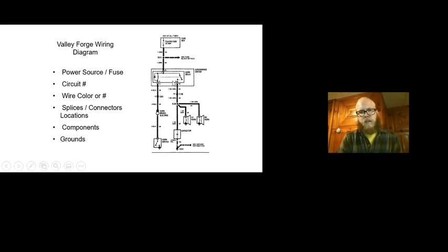On this, you see how the fuse panel is all dashed. That means we're only seeing one piece of this fuse box. There's much more going on, so they make this dashed line around it so that we understand it. The same thing is happening down here in this convenience center where the relay is located. Here's a splice, and then you see these dashed lines here. That means there are multiple wires that come out of that splice.